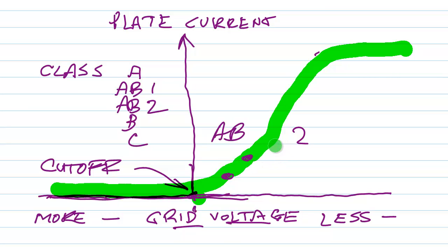Radio frequency linear amplifiers typically operate in class AB1 or AB2. The RF waveform itself, that is to say the signal wave, does get distorted by this type of operation, but the modulation envelope, that is to say the voice print or whatever other amplitude modulation you may apply, music, voice, whatever, remains faithful to the input modulation envelope.